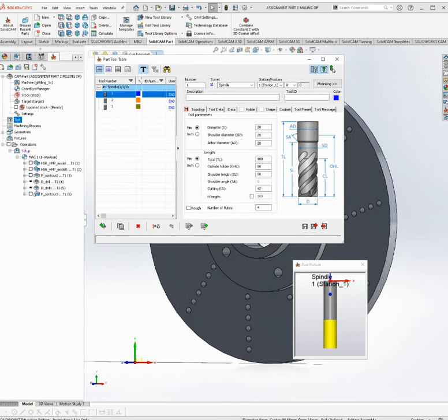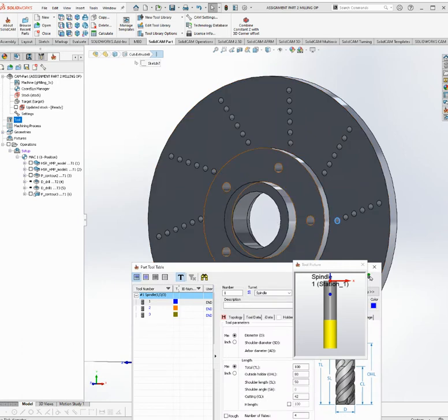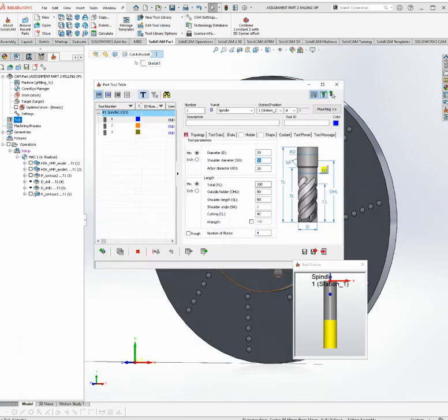And so the first tool, it's an end mill, I selected with diameter of 20 for the main surfaces, so milling down the surface, and for the big hole as well. And since it's going through 40 millimeters, the whole disc, it's better off to increase the cutting length to 42, so it does not stop in the way of the machine, any of the part, to damage any of the parts, and it doesn't crash when we're determining this.